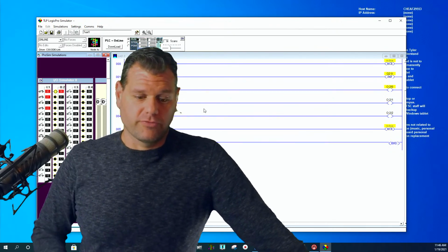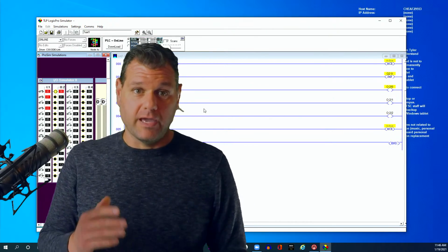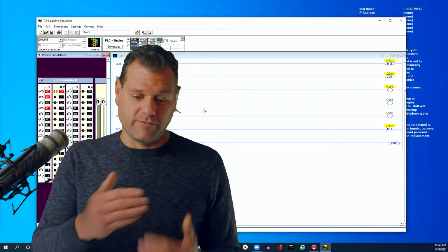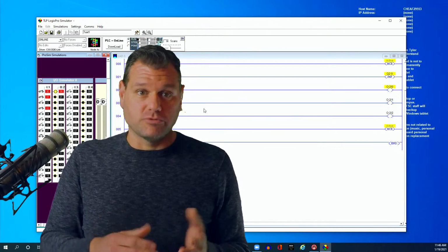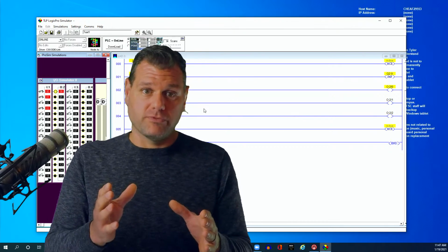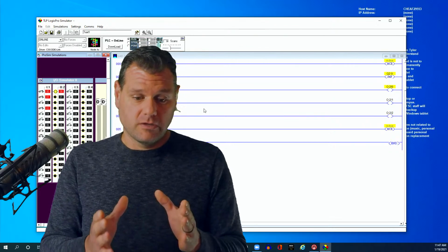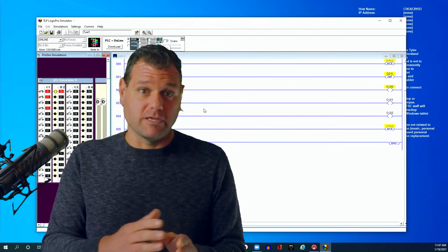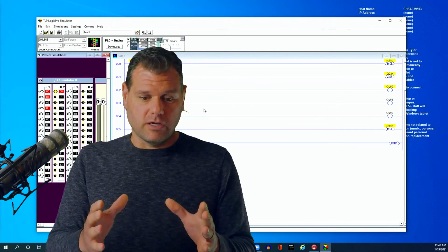That is correct. So the MCR fence only affects the stuff within it. And like I said earlier, the rule of thumb is you never jump into an MCR fence. As a demonstration, I'm putting the jump within it, but it's really not advised, because once the MCR goes off, you lose the function of that jump if it's inside there.